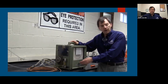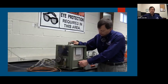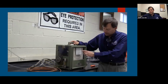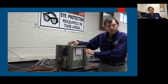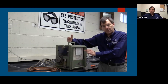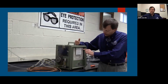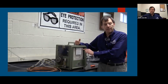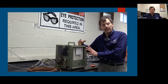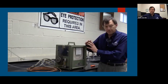When I move this unlock switch to unlock and I unlock the needle, you will see the needle come down from its lock position, which is just up inside past this label here. Because I am pulling air through the machine on the measuring side and air through the machine on the reference side, I should be getting a specific gravity of 1.00. It may take a few seconds for it to get to that point because it has to purge out everything that was in the machine in the first place.